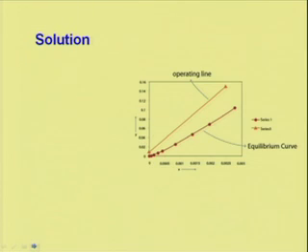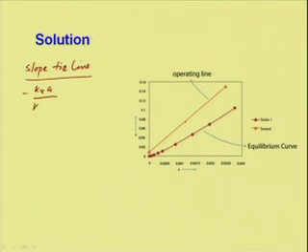So, now the procedure to be followed: we will locate a point anywhere on the curve, and the slope of the tie line can be calculated as minus kxa divided by kya, which is equal to minus 1.1 by 0.07, which is equal to minus 15.71. This is the equation of the tie line.